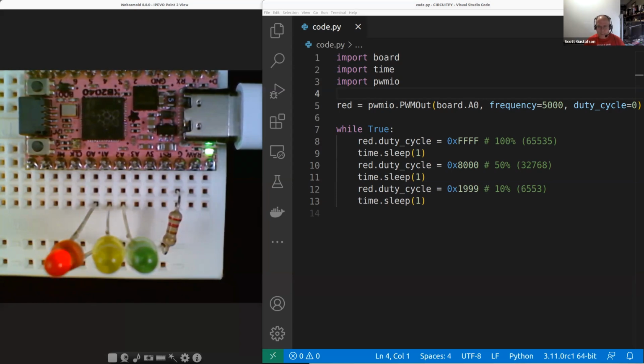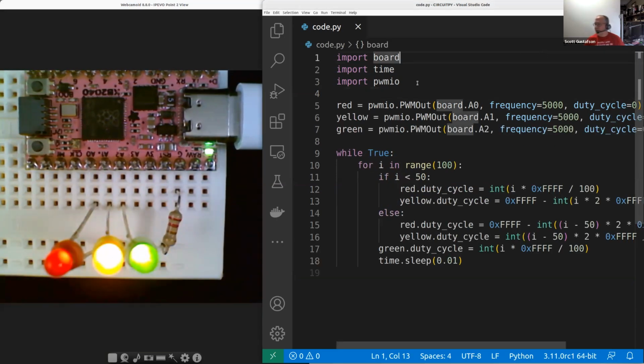So another example, and I'll drop the last one here, PWMs. I'm just replacing the code again. So now I have red, yellow, and green, 3 different PWM outs. And I'm using 3 different PWM channels in this microcontroller. They're all independent of one another. I'm setting the duty cycles to different things so that all 3 can run at different scales and different speeds. So you can see that there are 3 full PWMs going out.